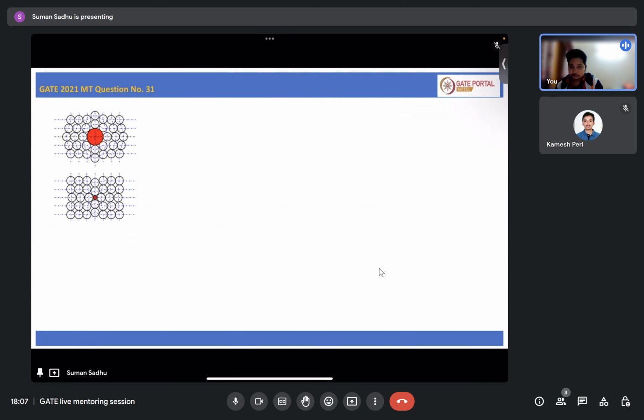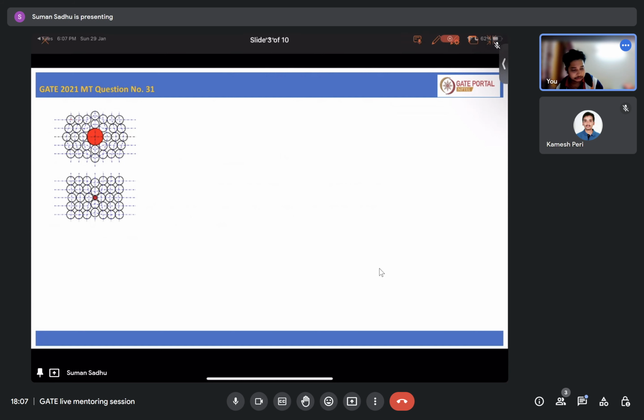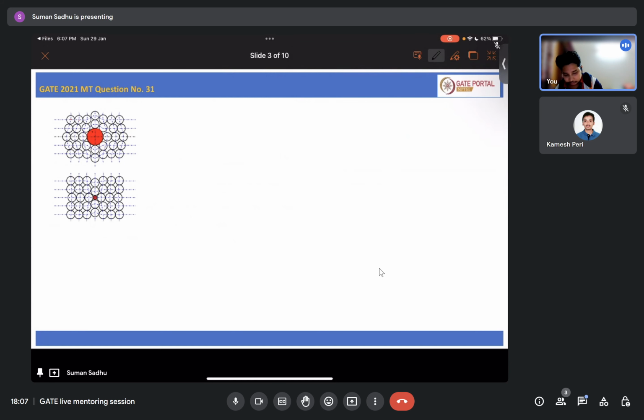So as you can see from this diagram, these are the regular size of the atoms in the matrix which you have. Now one oversized atom is dissolved here. Because of this oversized atom, it is developing compressive stress in the area surrounding it.